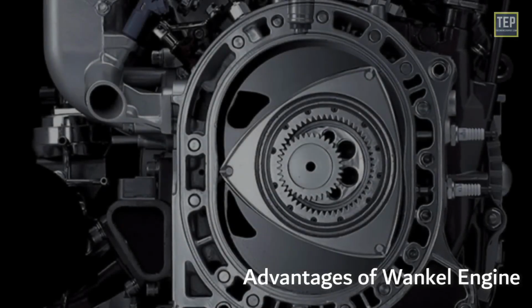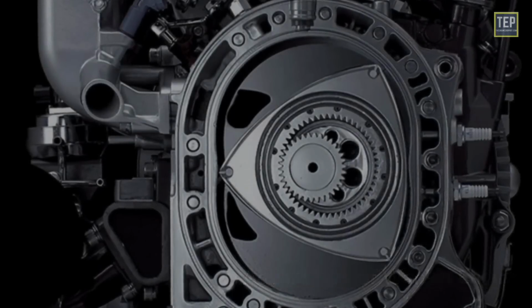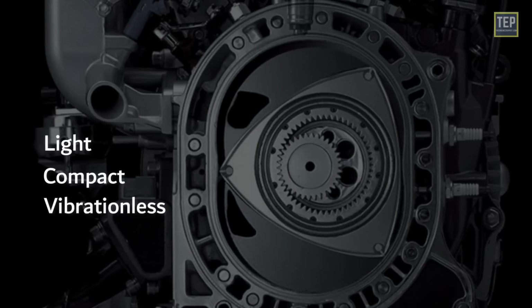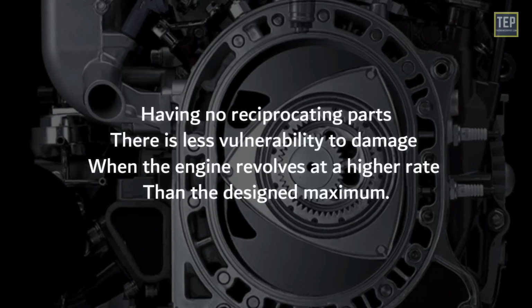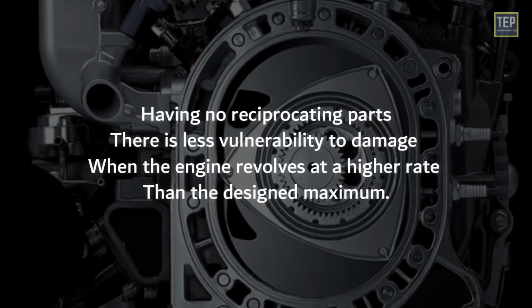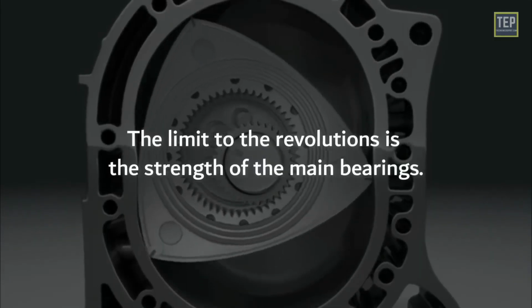Now let's take a look at advantages of Wankel engine. In principle, Wankel engines are ideal for light aircraft, being light, compact, almost vibrationless, and with a high power-to-weight ratio. Having no reciprocating parts, there is less vulnerability to damage when the engine revolves at a higher rate than the design maximum. The limit to the revolutions is the strength of the main bearings.